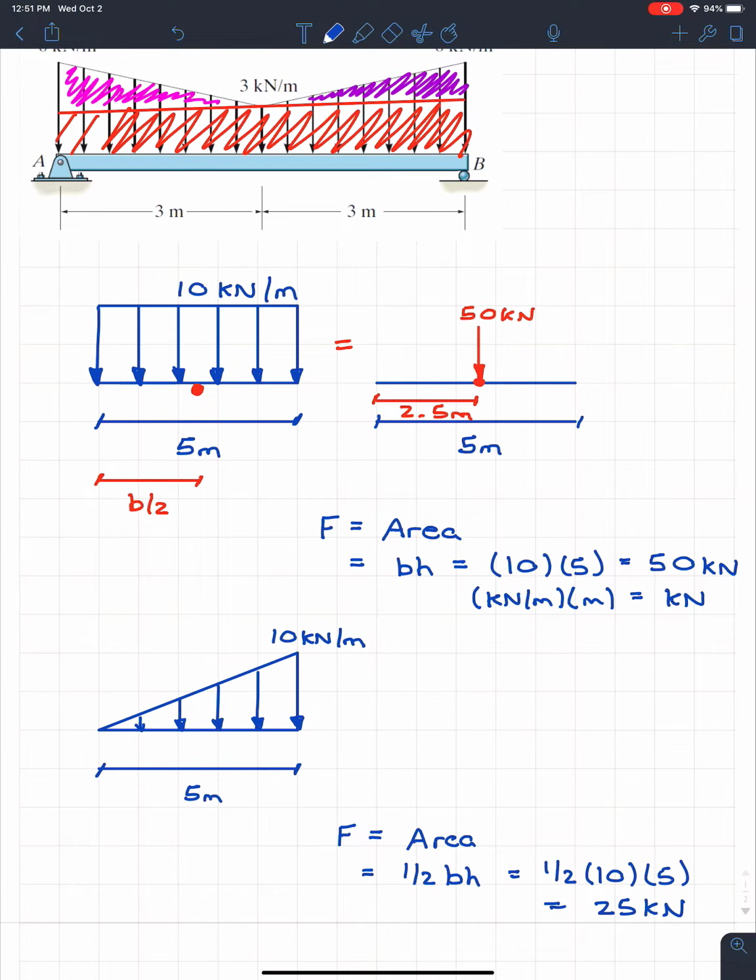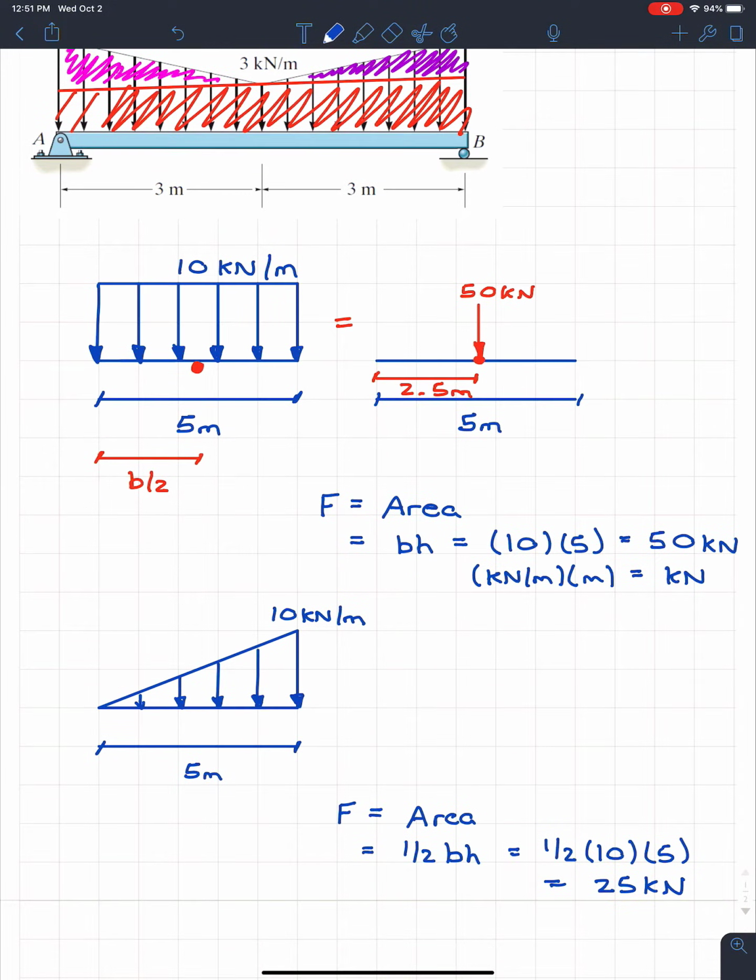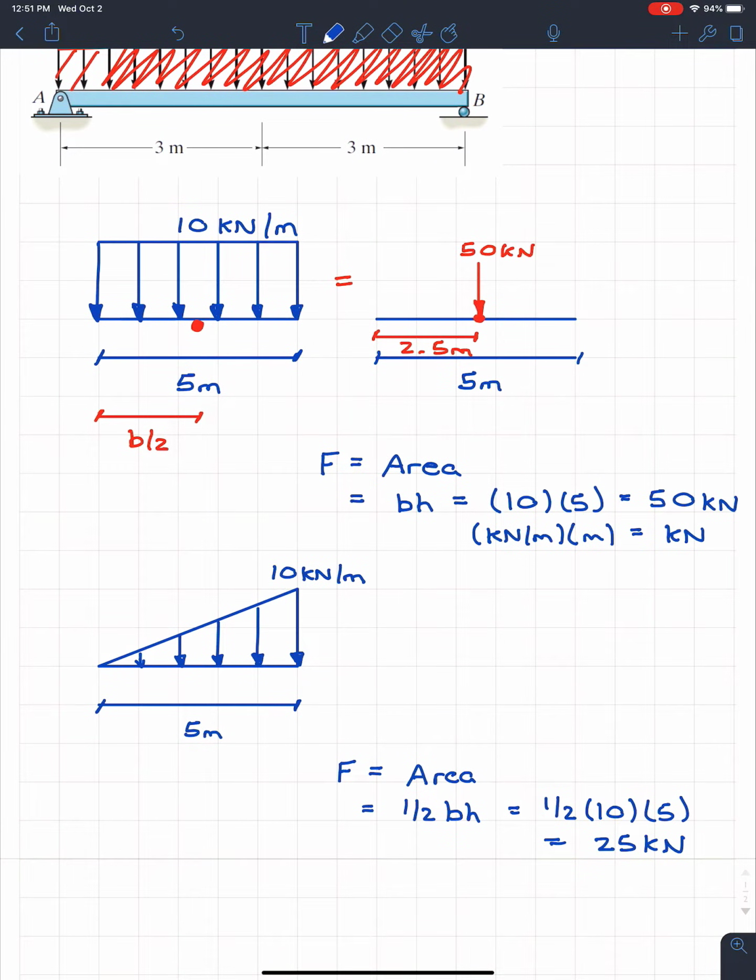It's not that hard, Clayton. And yes, that's true. It's not that hard. But for those of you who don't know, you're going to have to just kind of memorize this, which is nice. Actually, I think your formula sheet may have the centroid of some shapes on it, which is good. But I'll tell you this now, and you guys will always have to remember this: the centroid of a triangle is 2/3 from the small side.